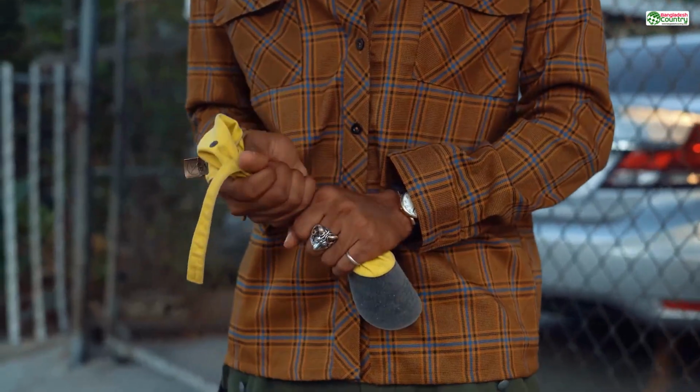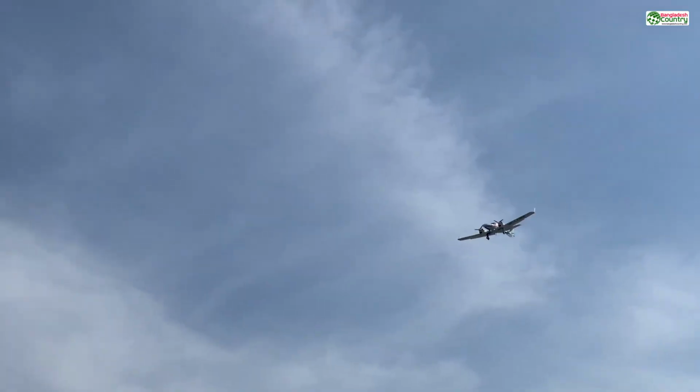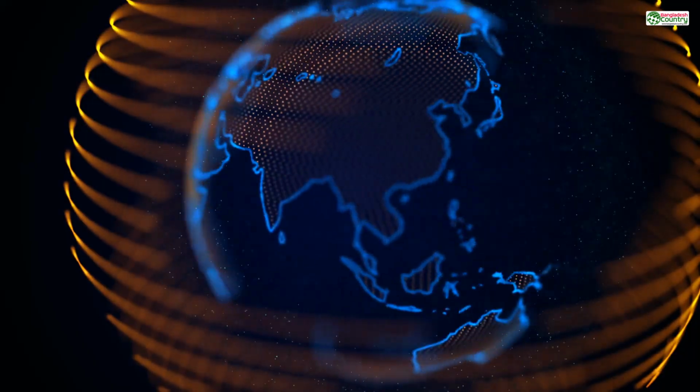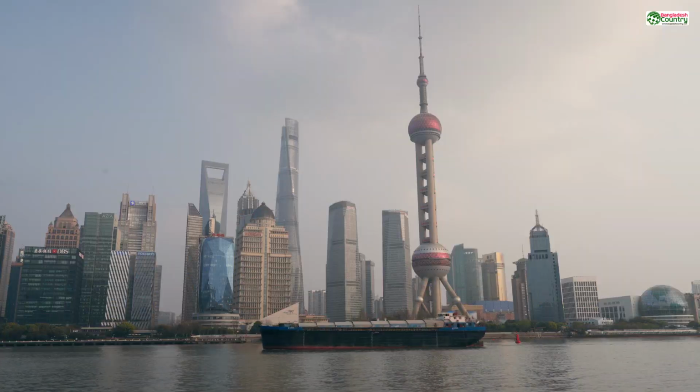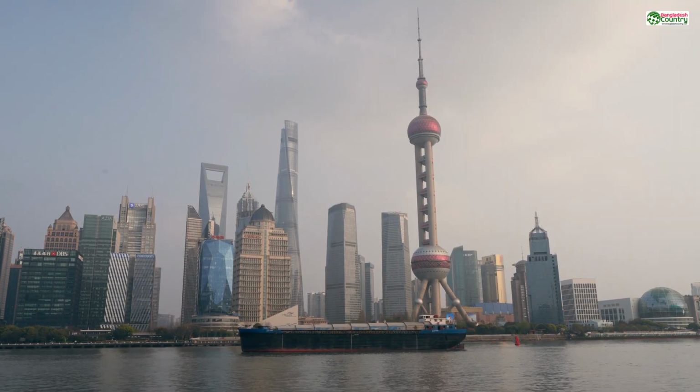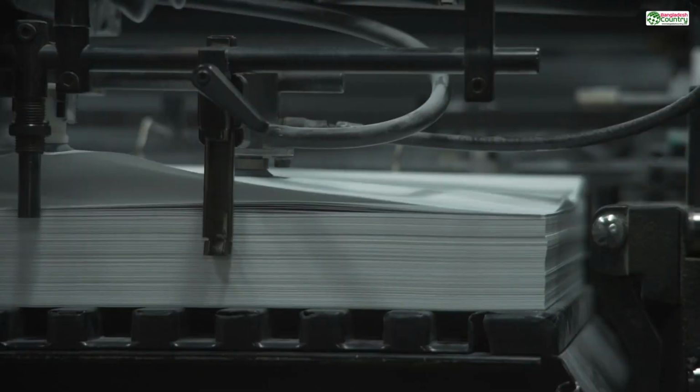And the fourth and final culprit is the zero-thickness wall, also known as a 2D surface. This is a wall that is infinitely thin. It's a plane that has area but no volume. In the digital world, you can create a surface made of a single face. But in the real world, you can't build a wall out of something with no thickness. You can't 3D print a sheet of paper that is literally 1 atom thick.